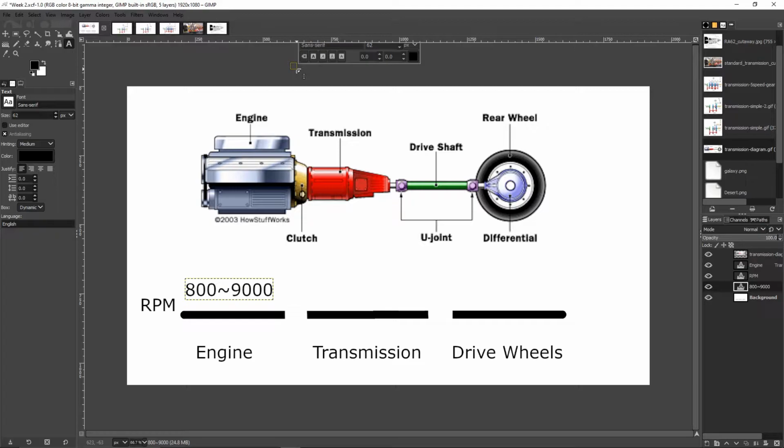That's really the reason we have rev limiters now, is the computer just won't let you go beyond whatever is safe for this engine. The other thing that happens is you could spin a bearing. When we removed the crankshaft from that engine in the lab last month, and I showed you guys those half circle shaped bearings, the bearings were in the main caps. And when someone says, hey, I spun a bearing, now my engine's knocking, that half moon, half circle bearing will literally rotate up into the block, not where it's supposed to be, not creating the correct oil pressure, not lining things up, and that will really ruin an engine quickly. So this is important.